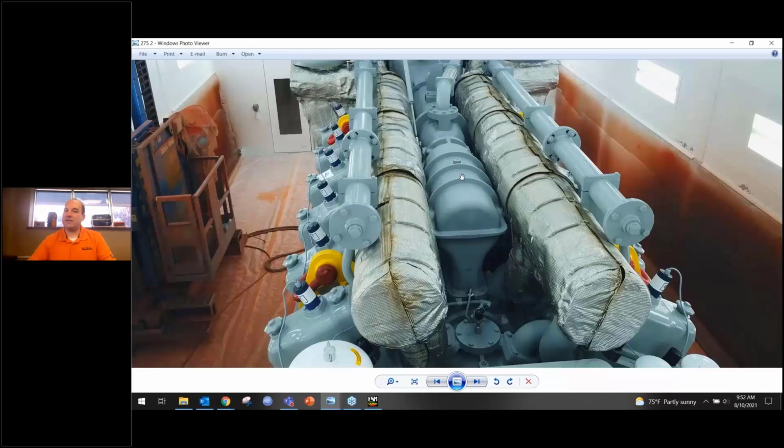The 275 is a little different from our other engines, where the intake manifold and the exhaust both exit the engine out of the center of the V. So if you don't have this insulation on there, you can actually run into high intake manifold temperature. This is just a quick one, but some good guesses out there between the harness connections and whatnot. It turned out in this instance it was just related to the insulation not being reinstalled.